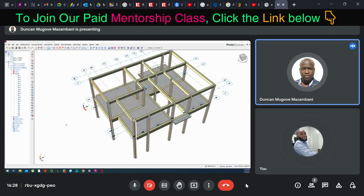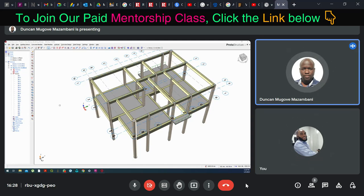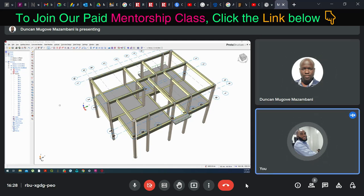Okay, so whenever you don't have your slab on the roof beams, you have to subtract that slab depth from the roof beams. All right. So right now we go back to plan view for us to adjust what we have.